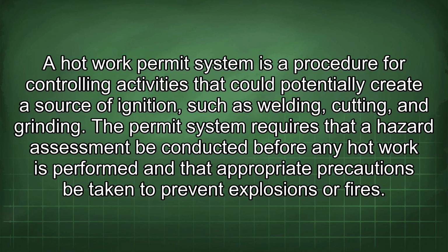A hot work permit system is a procedure for controlling activities that could potentially create a source of ignition, such as welding, cutting, and grinding. The permit system requires that a hazard assessment be conducted before any hot work is performed and that appropriate precautions be taken to prevent explosions or fires.